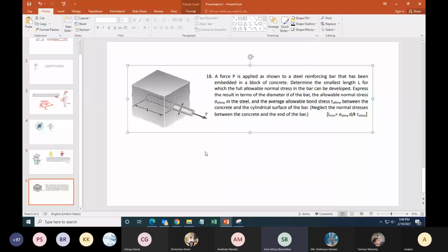Sir, normal stress does not depend on the length. It depends on diameter. No, we have to find out till it breaks, shear stress and for normal stress, and then we have to calculate. We have to equate both. Yes, both the quantities should be reached together.